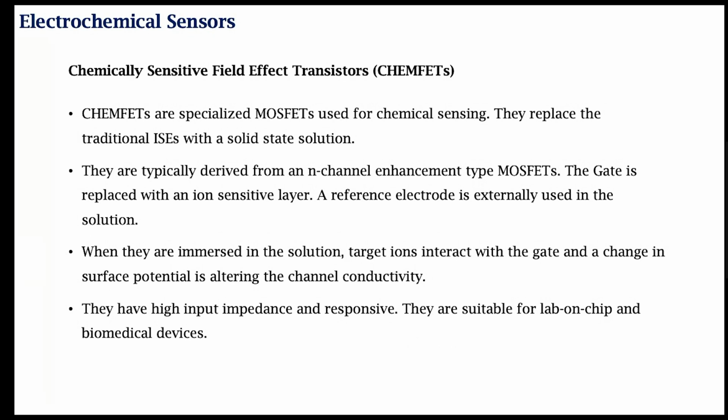That way I can actually straight away measure the concentration transfer function, concentration of a given ionic species, right? So the gate of the FET is replaced with the ion sensitive layer, and is used in the solution.